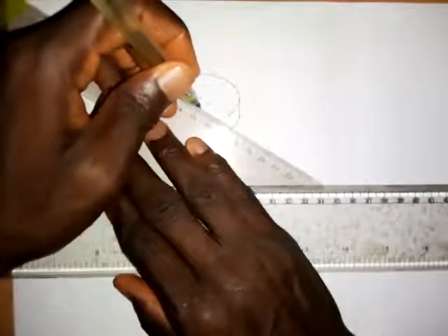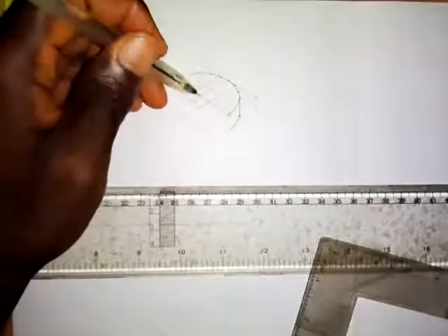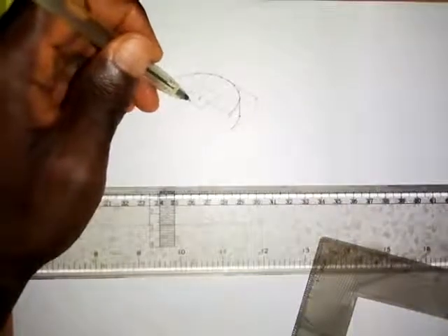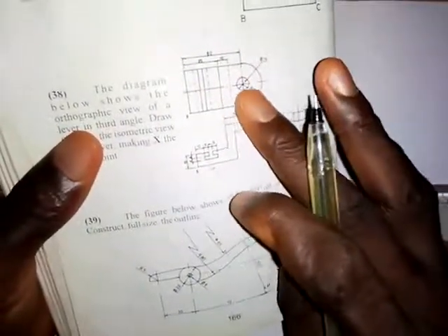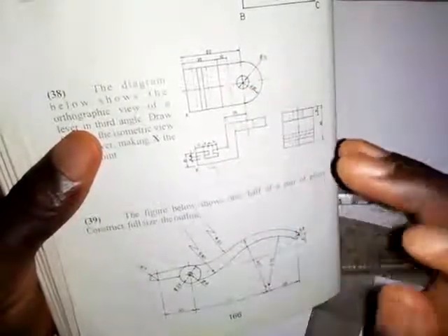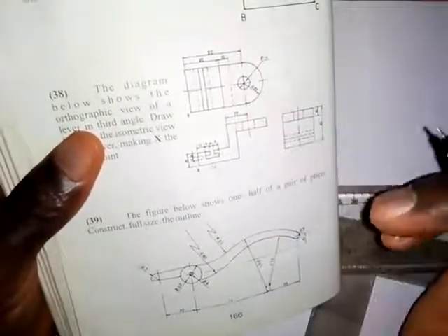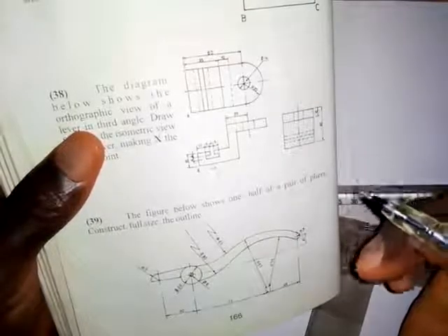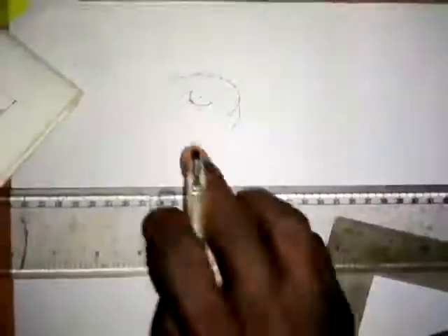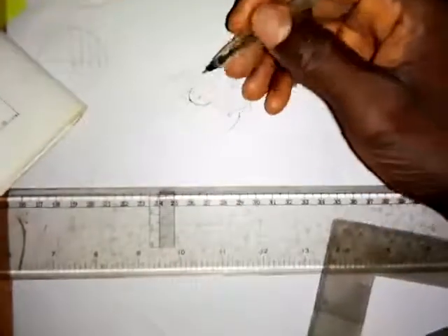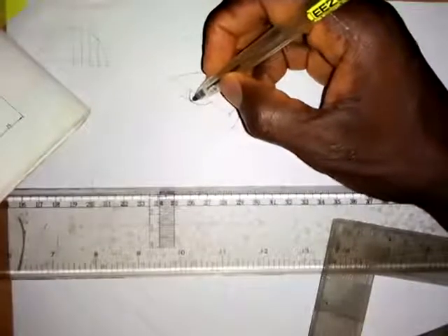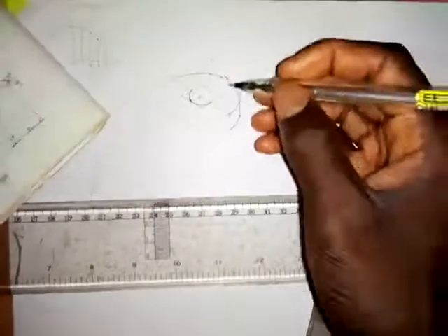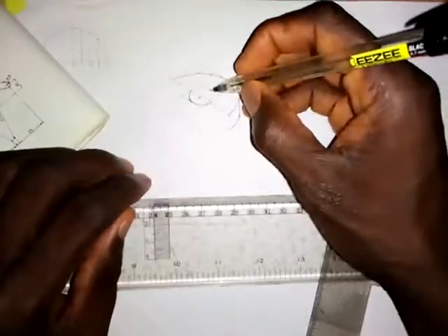Okay, so this is the square. All right, so the next thing I'm going to do is that, when I have a small circle on an isometric object like this, what I usually do, after drawing the circle and the square, is use my hand to join the 4 points together. What I mean is this: I've done 2 out of 4. I've drawn an arc joining this point and this point together, and from here to here I've joined this point and this point together. So the next is that I'm going to join this point together with this point.